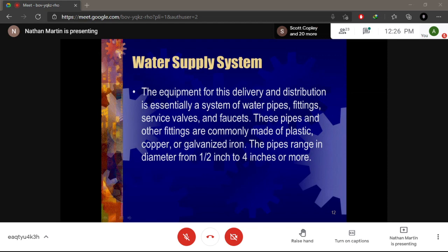For your typical home or typical size facility, you will mainly find ½ inch. Now, if the facility is large, your incoming pipes can be up to 1 inch and an inch and a half, and then they'll use a reducer bushing to reduce it to the ½ inch to take to the different locations, right? And this actually improves the water pressure of the facility.